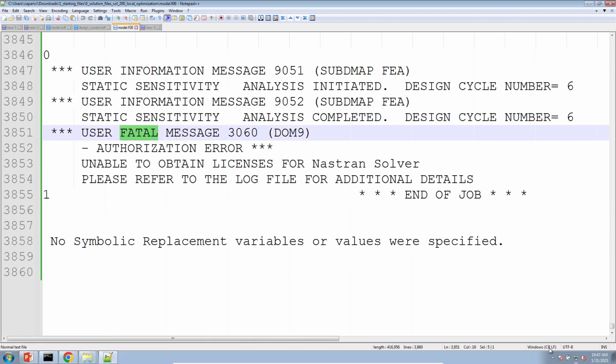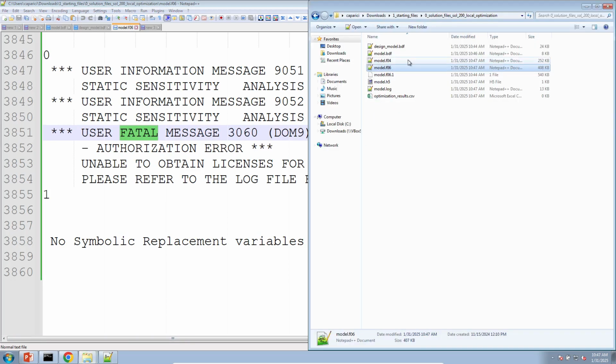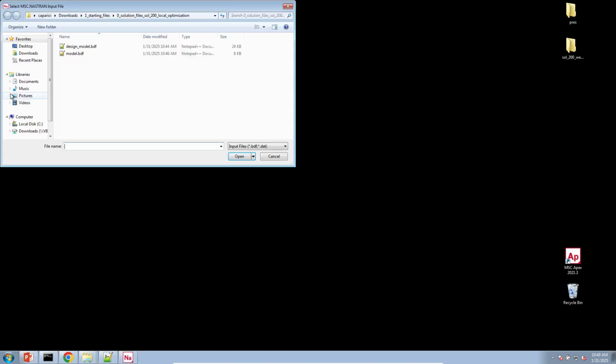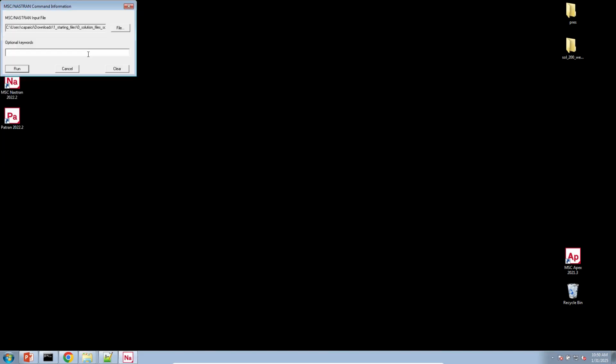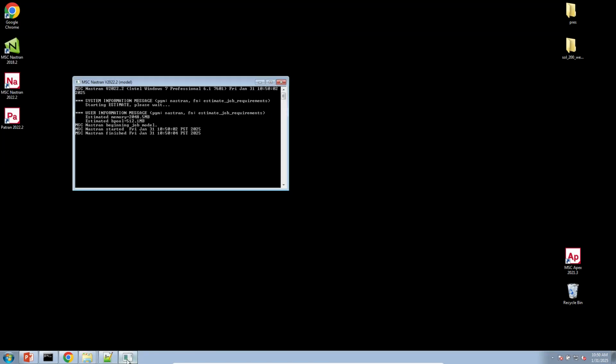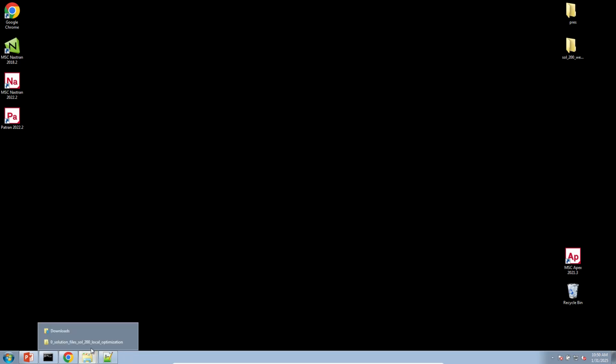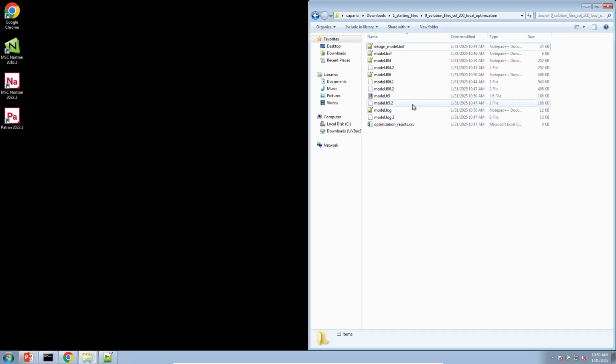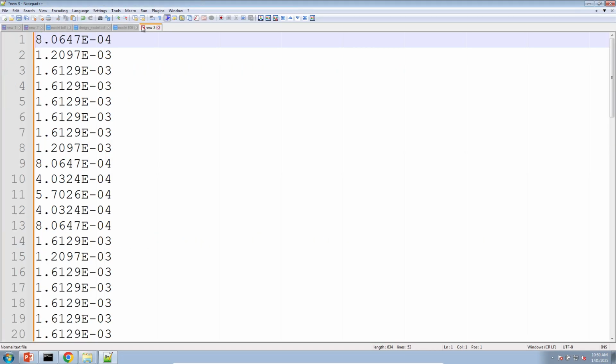Oh, and it seems like there is a problem with my licensing. So let's go ahead and see if I can figure this out. Let me pause the video because I think I need to restart my license server. Okay, I restarted my license server. Let's try this again. Sometimes what happens when you run Nastran hundreds or thousands of times, one of those executions holds the license and doesn't release it. So let's go ahead and look in the F06 file and see if we get results here.